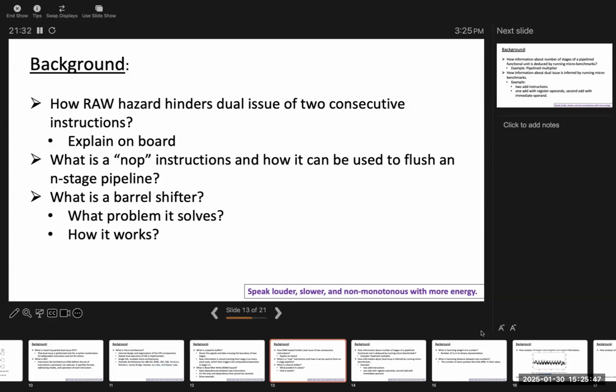Let's say I want to do the left shift operation by an amount of 1. After the operation, the new content of the register will be like this. This bit will be thrown out because I'm doing a logical shift. When you do the arithmetic, it is a bit different, but I'm doing the logical shift operation. So this will be thrown out and everything will be shifted by 1 position towards the left. The least significant bit will be filled with 0.